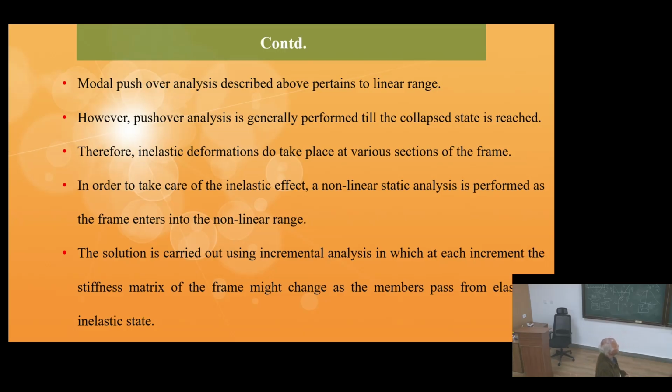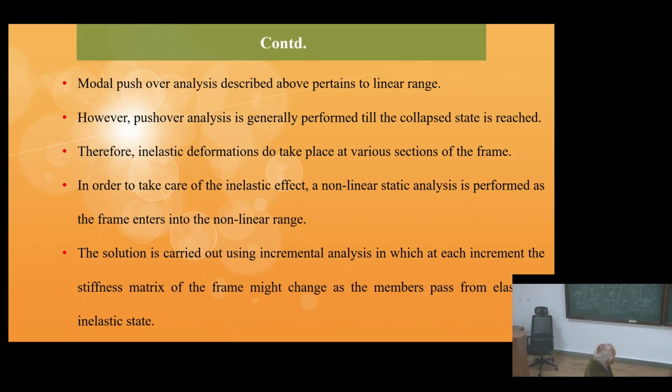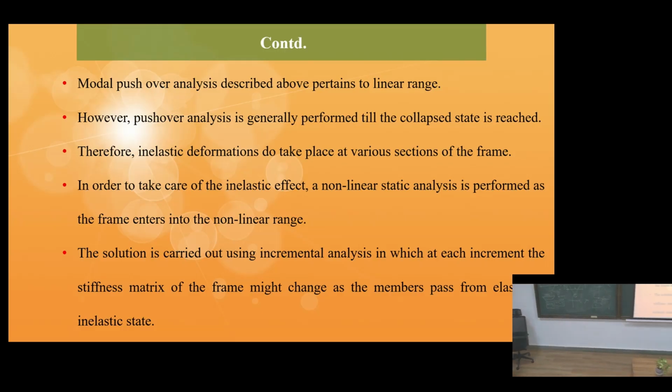In order to take care of the inelastic effect, a nonlinear static analysis is performed as the frame enters into the nonlinear range. The solution is carried out as an incremental analysis in which at each increment the stiffness matrix of the frame might change as the members pass from elastic to inelastic state.